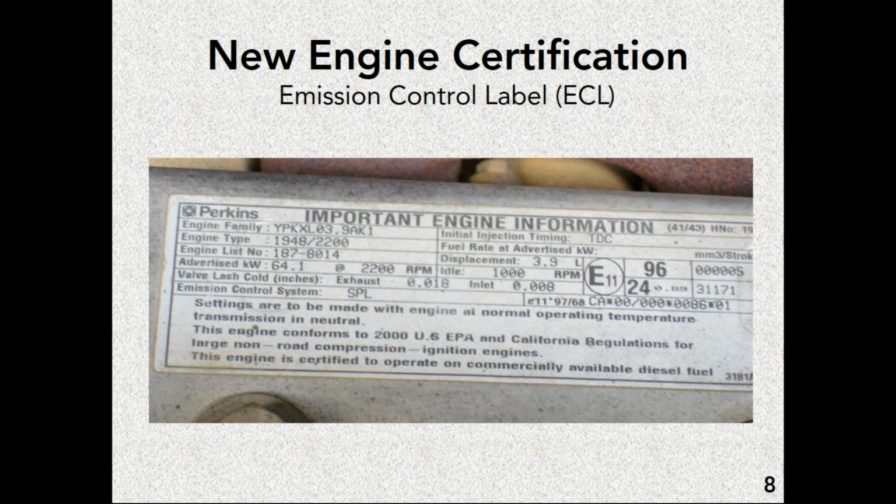And then the next 4 digits, 03.9, some of you are already way ahead of me on that. That is the displacement of this engine. So that gives you the size of the engine itself. In this case, that decimal point happens to be one of the characters that we count as part of the family name. And this is a 4-liter engine. AK1, the last 3 digits, are where the manufacturer has some flexibility to designate this particular engine class. That is their designation for this engine.